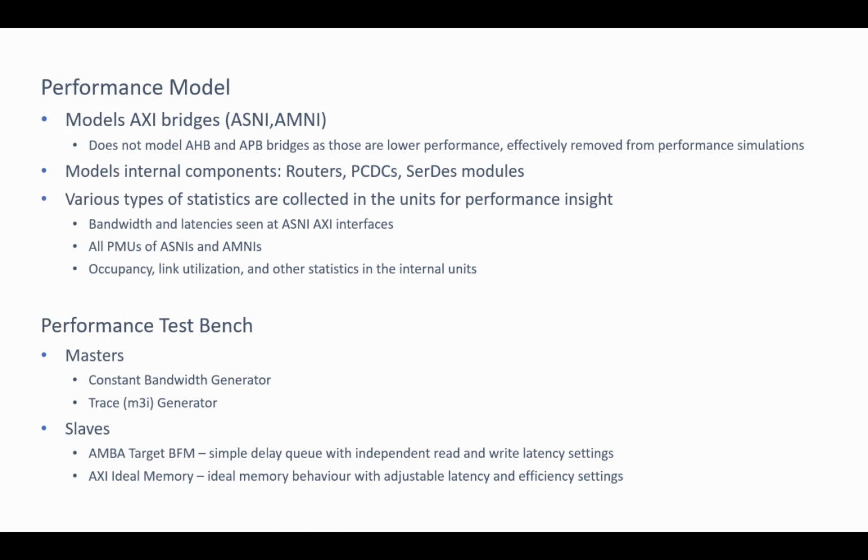The performance testing application provides a set of tools that allow you to model different traffic scenarios and measure performance. You can set up different test cases, run them, and view the results. The application models AXI bridges, so ASNIs and AMNIs, and internal components such as routers, BCDC, and SerDes modules. It doesn't model AHB and APB bridges, as those are for lower performance traffic and are typically not a concern